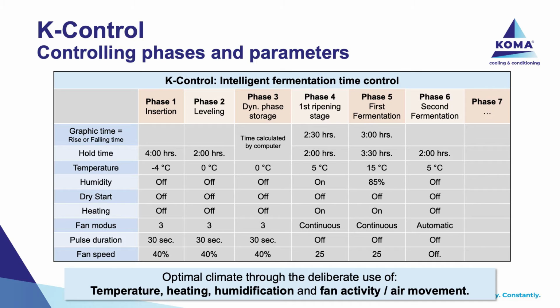As an example, for these kind of products, we took a drying period, which we left out because basically you need to keep the stable humidity temperature of the room itself intact. Therefore, you can program air speed continuously, but also in automatic speed. That's what you see in the separate phases. To conclude this slide, basically 6 phases: temperature, humidity, air speed, continuously, automatically, dehydrate, yes or no, all parameters you can adjust to your specific product.